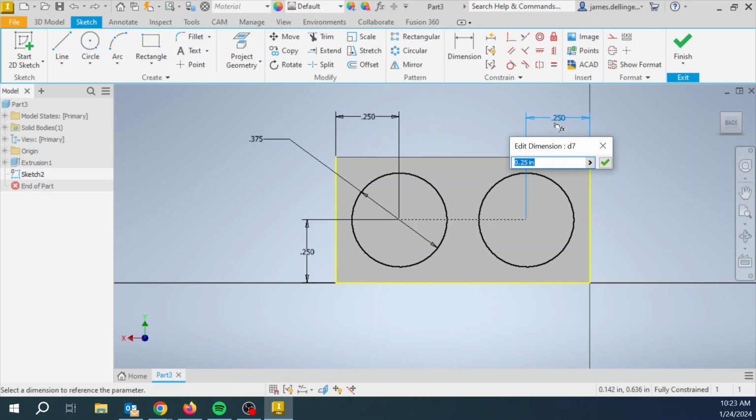All right, the neat thing is Inventor will allow you to do formulas, right? And so you can say equals. So double click the thing. I'm going to start over. I feel like people got lost. Double click it to edit the dimension. Hit equals, and then say, hey, that's equal to this. And so it makes a function.